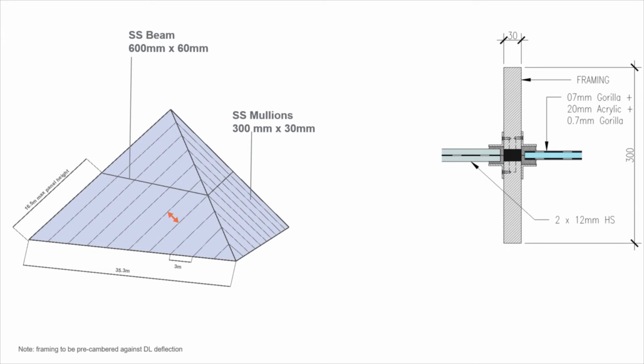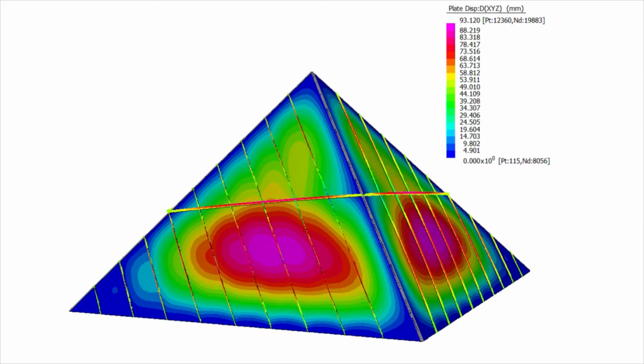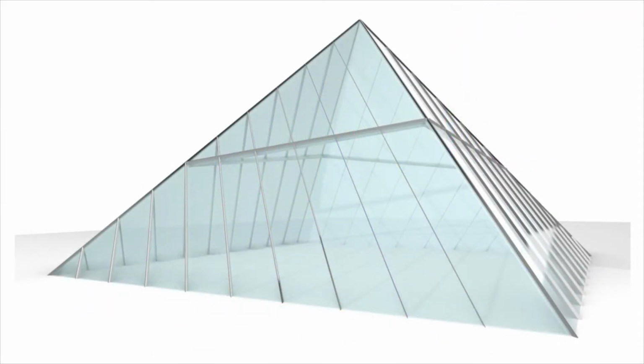So taking it one step further, we added a secondary ring beam to try to break up the spans a bit more and get sizes to be a bit more slender. And again, what we landed on was something that, although it has somewhat smaller steel sizes, is really not a huge departure and not a huge increase in transparency.